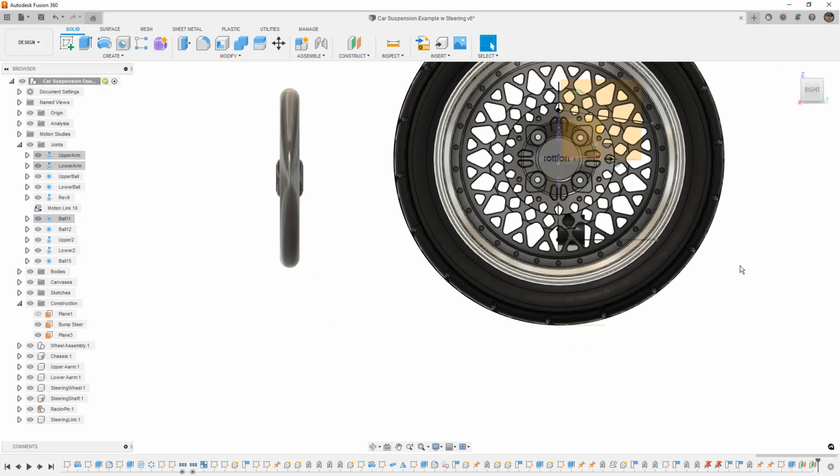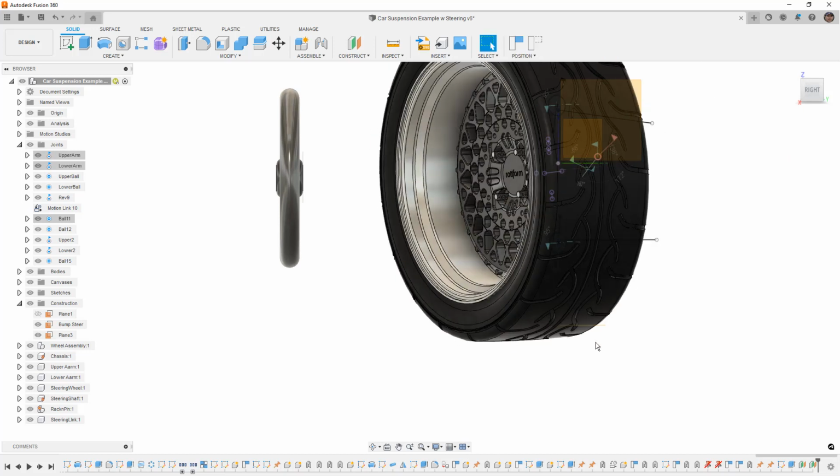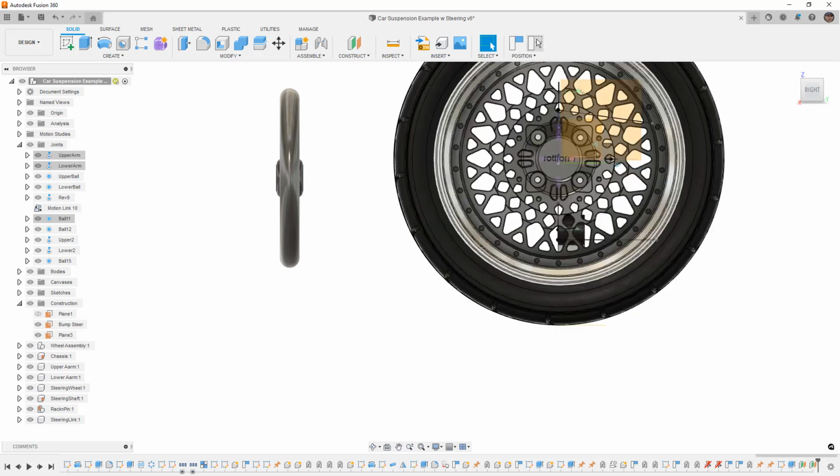That's pretty close. One thing that we need to make sure we understand, when this moves, we want to make sure that that plane doesn't move. Now, if we capture position, think about this in the context of the timeline, that capture position would happen after the plane was created. So as long as that's true, that plane should always stick where we put it. And I'm going to call this one my ground plane.